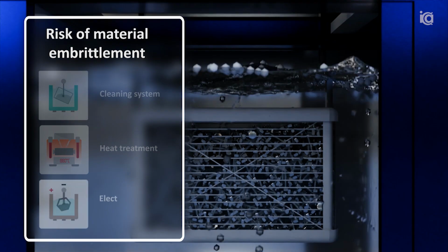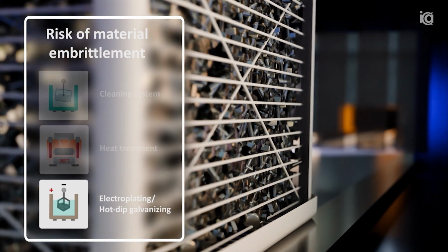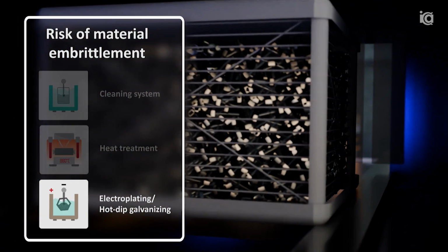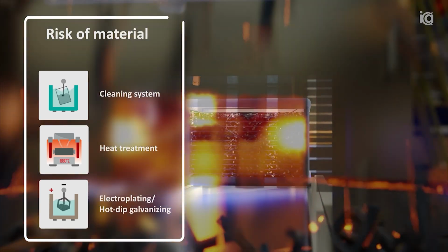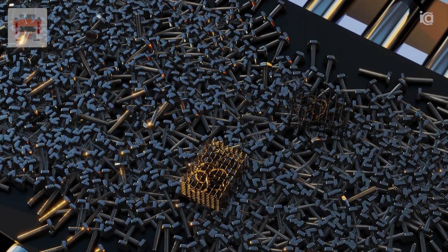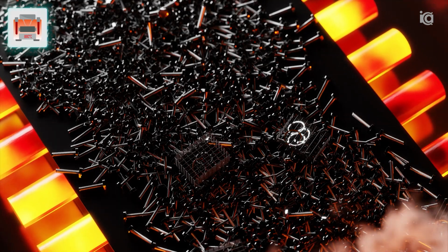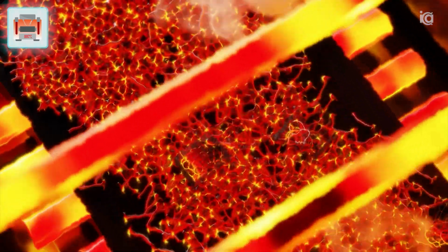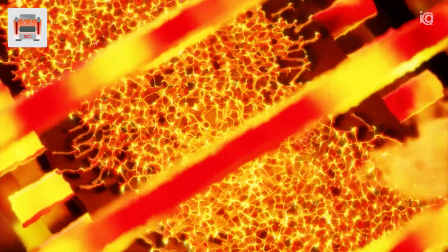On the other hand, the production-related material embrittlement induced by hydrogen comes into focus during the pre-treatment and deposition of chemical and electrochemical surface coatings. Incorrect heat treatment can lead to so-called 300 or 500 degrees temper embrittlement. The resulting diffusion processes cause material embrittlement, for example in locations around grain boundaries. This can reduce the binding energy of the material and may result in critical component failure.